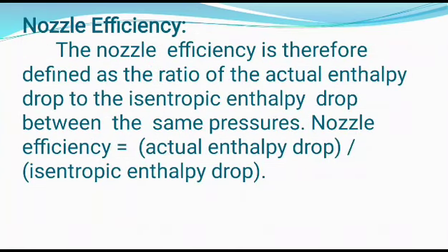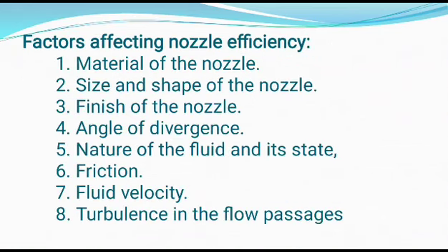Next one is nozzle efficiency. The nozzle efficiency is defined as the ratio of actual enthalpy drop to the isentropic enthalpy drop between the same pressures. The formula for nozzle efficiency is actual enthalpy drop divided by isentropic enthalpy drop. The factors affecting nozzle efficiency.